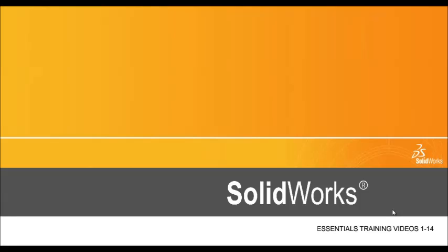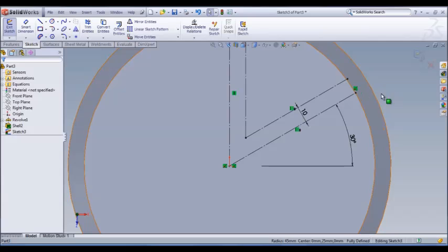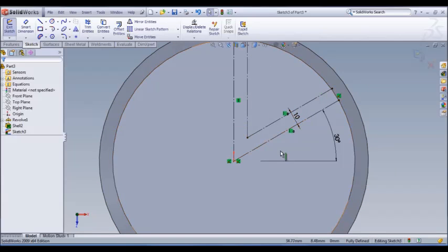So for example, as we've seen with the rib feature, where we can create a very simple sketch and then create a solid feature with it, that feature also automatically has the integrity to understand that it's touching a curved surface and follow that surface where a normal extrude wouldn't. We can use sketched features like slots that will automatically vary themselves depending on the circumstances of what they're interacting with. So to make that make a little bit more sense, I've drawn these construction lines here for